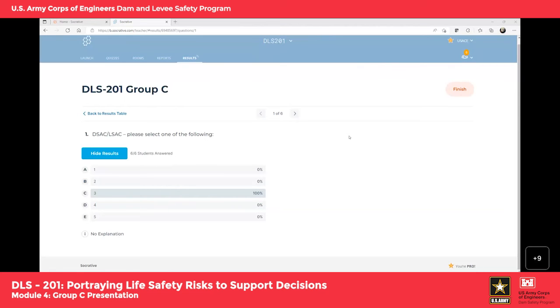I kind of looked at it a little bit, Adam. With both failure modes, you kind of got to look at the total risk for DSAC. Both of them independently were under the threshold, but both of them together were over. So I looked at it a little bit, but mostly looked at the combined little FN chart for my determination.